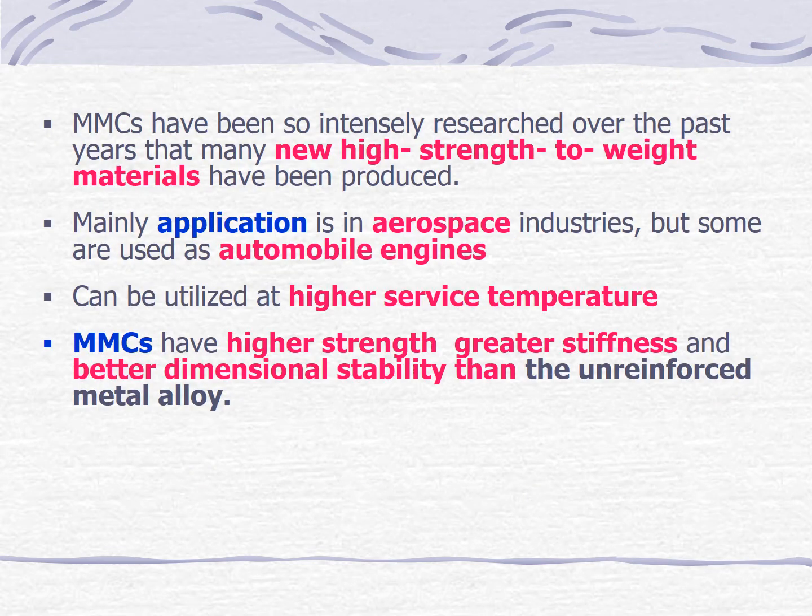Okay, MMCs have been so intensely researched over the past years that many new high strength-to-weight materials have been produced. The main application of MMC is in the aerospace and automotive industries. It can be utilized at high service temperature. MMCs have higher strength, greater stiffness, and better dimensional stability compared to the unreinforced metal alloy. That's why we produce metal matrix composites.